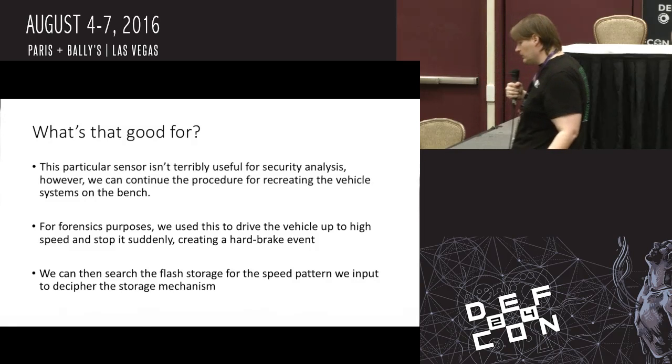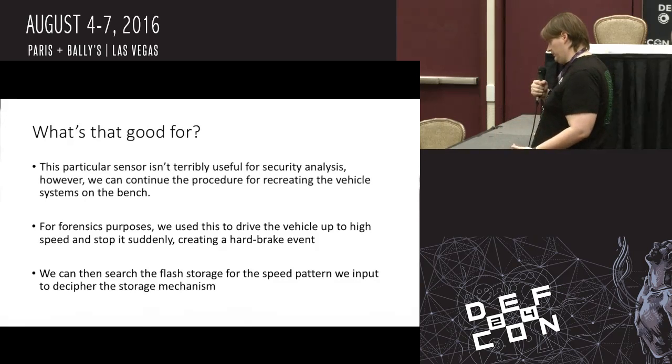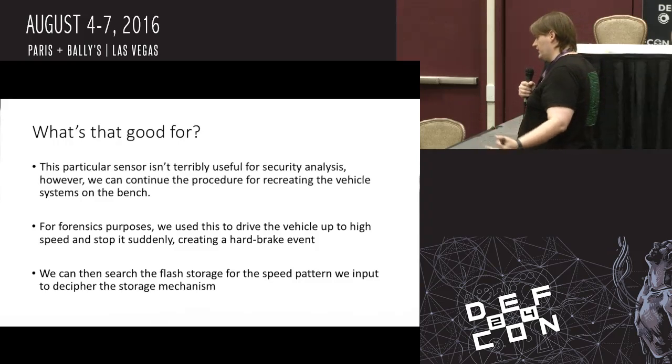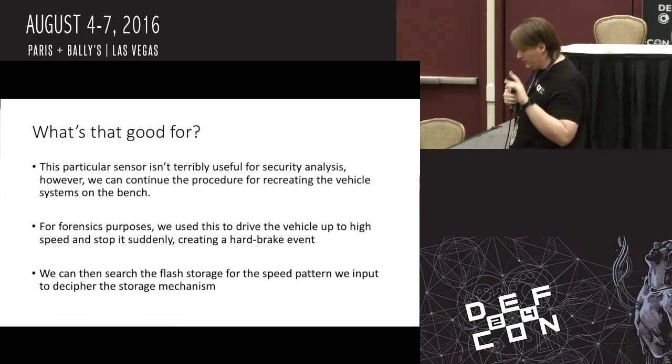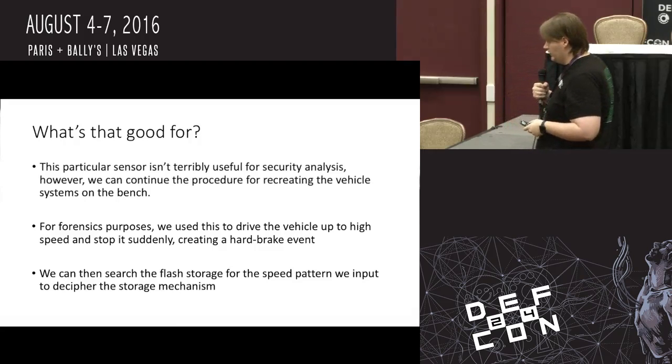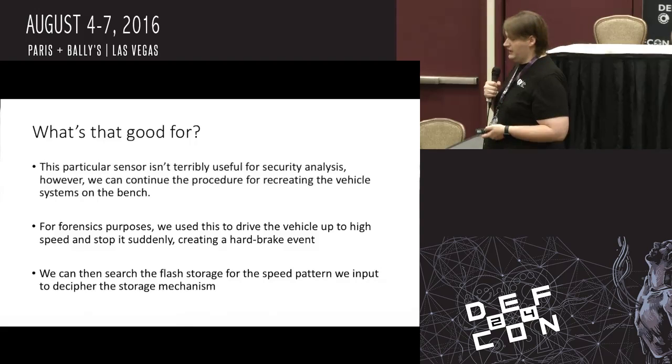So we can use our fake vehicle speed sensor to put in a pattern that we know what it looks like, run the ECM through that simulated driving pattern, and then slam on the simulated brakes, and the vehicle will record that as a crash or hard brake event, and then we can go fishing around in the flash memory for that pattern to see how it stores that data.